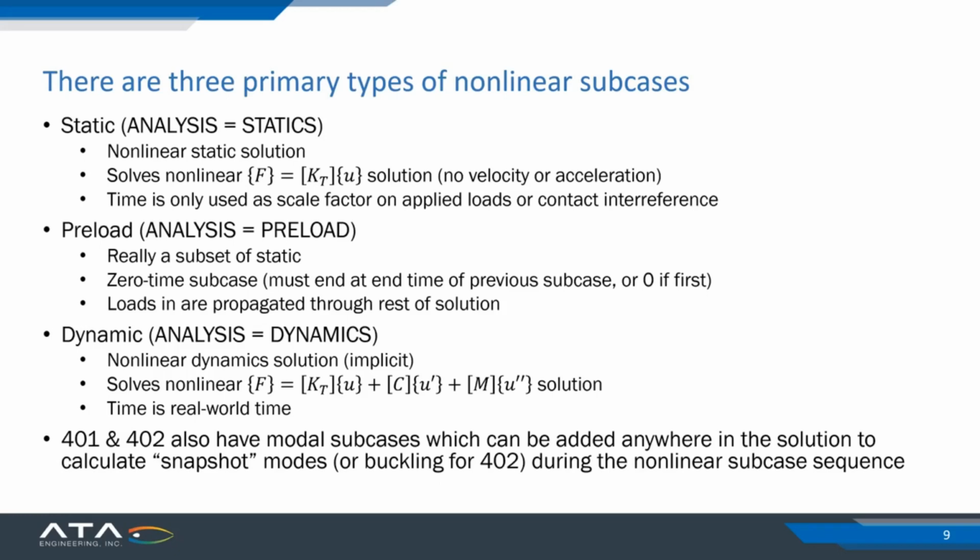And then lastly, there is the dynamics type subcases, which is your implicit dynamic solution if you're using that. So that's your full equation of motion where you have your displacements, velocities, and accelerations considered, and your time is a real world time factor. So you might use that if you're doing a drop test simulation, for example, where you have a thing that hits a hard surface and then bounces around, and you're looking at the response dynamically to that impact event.